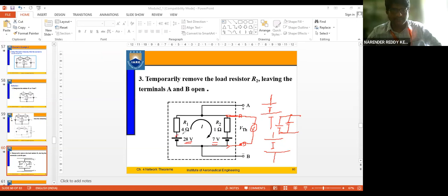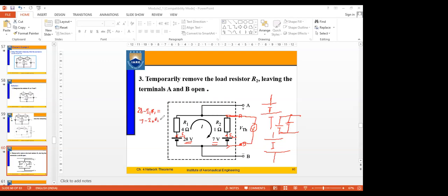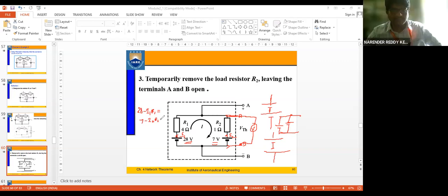since this is a source, this will be delivering one current, and this is another source. Let us assume this is delivering another current. So the condition, or justification, we can make here is that any voltage drop, that is 28 minus I1 into R1, should be equal to 7 minus I2 R2. If I apply KVL, that will be the equation, right? Applying the KVL loop equation, that will be the equation for this loop. I think you can find the values of I1 and I2 here.